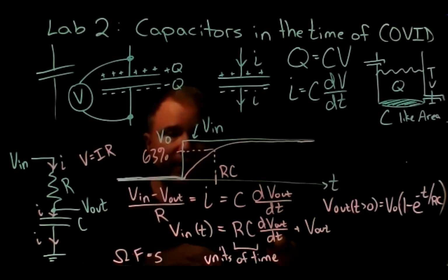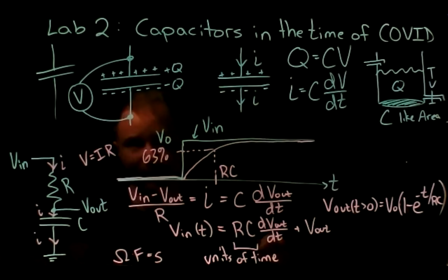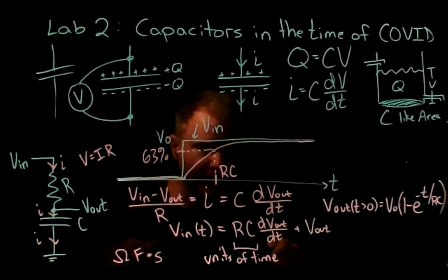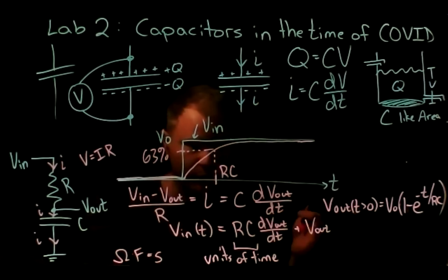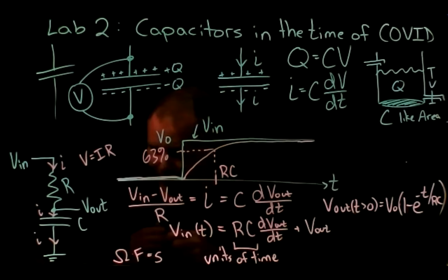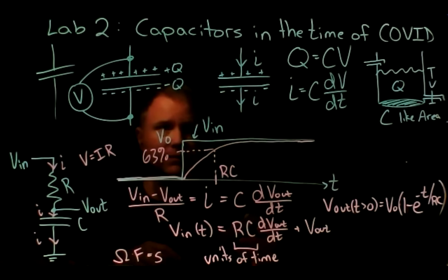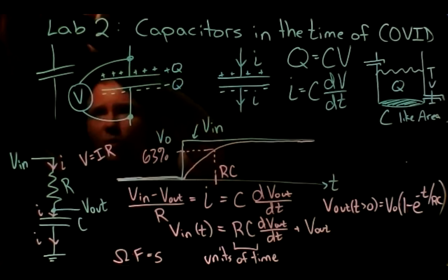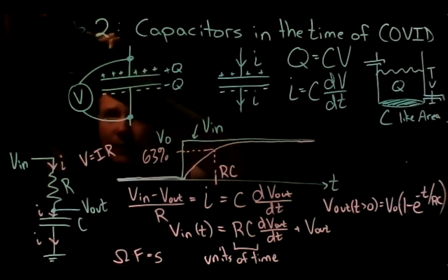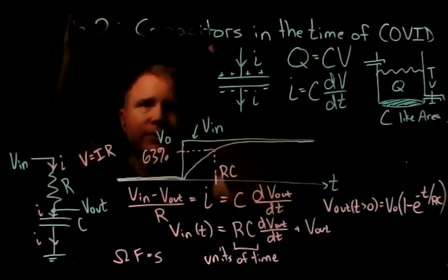So all the measurements you're going to make, all of the frequencies you're going to deal with, RC is the thing that sets the time scale. So with your signal generator and your oscilloscope, you can go from times that are seconds all the way to times that are milliseconds, microseconds, nanoseconds. There's just an enormous range. And so where do you even start looking? Well, unless you're looking at times that are roughly this order RC, you're probably not going to be looking at the right thing. So this is our first example here. Let me draw what happens when you put in a square wave rather than just a single step. And while I'm erasing, you can feel free to ask questions here.